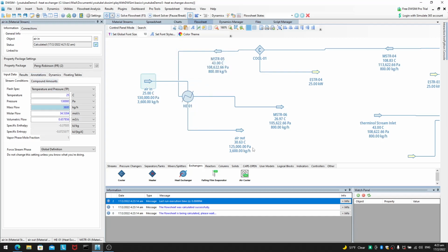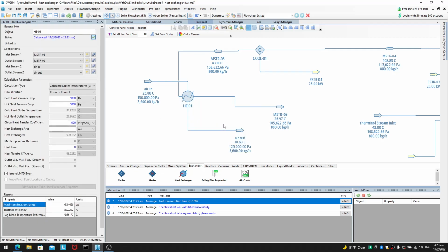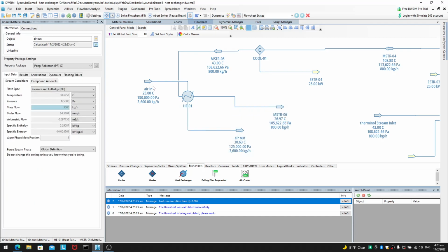As you can see, just now, the thermodynamic properties package here was in cold incompressible fluids. I have to change the properties package to Peng Robinson, and the thermodynamic property package must be the same for air in and air out. If not, you have this funny problem. So we found the bug. I guess that solves the mystery of why this temperature has increased. So we need to make sure the thermodynamic properties are exactly the same. Okay, that is very good. We should have this situation.